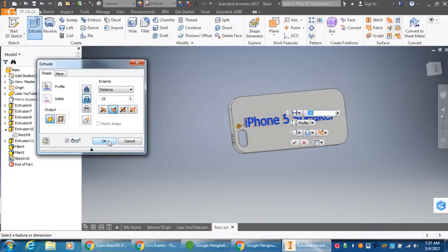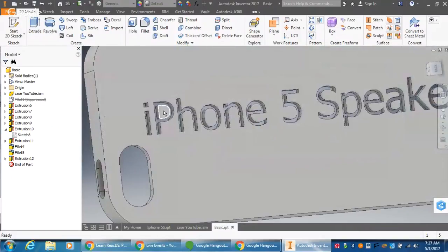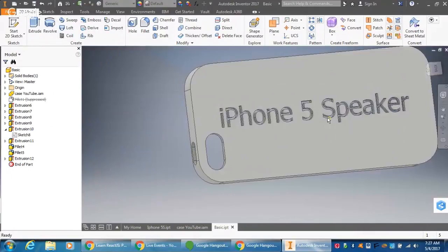But if I cut this all the way through, click OK, you're going to notice that I have pieces here like this P, all right? When you go to 3D print this, this little piece of this P is going to stick to your build plate, right? And you're not going to have a P. What you're going to have is a big open circle there. Same thing with this O. This O is just going to be a big open circle. This E, you're going to lose the inside part of this E. So you can't just use any text you want.